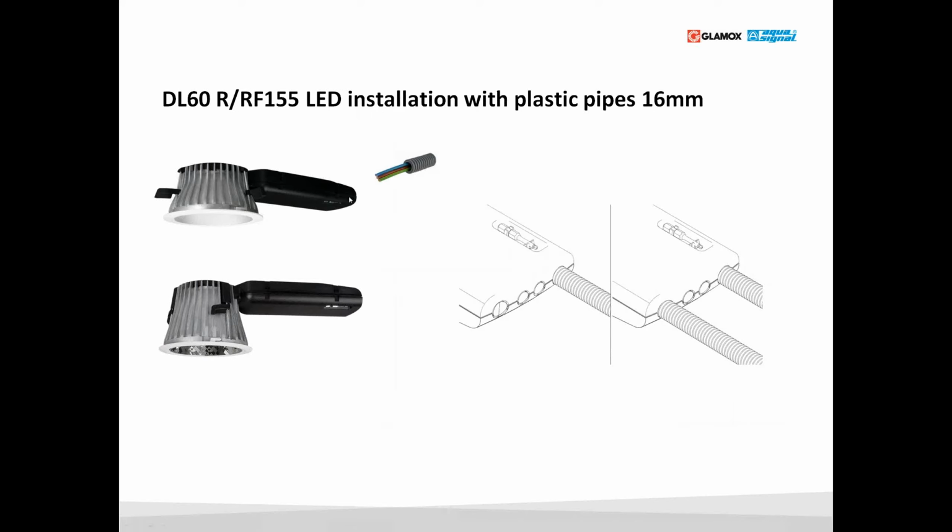It's also designed, when you are not talking about quick connectors, we also have a design for these ones, R108 and R155, that you can have a pipe, these plastic pipes, into the installations. So with the cables inside the plastic pipes. So it can take plastic pipes of 16 millimeters that can be integrated to the main body.